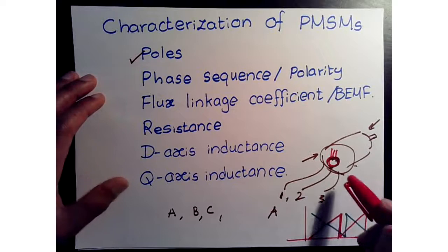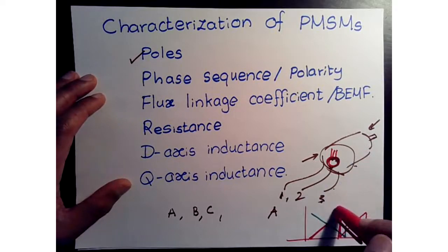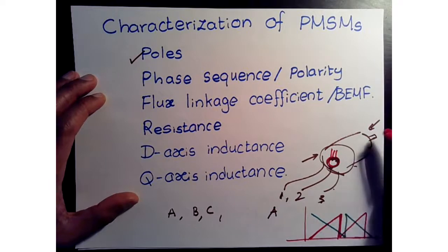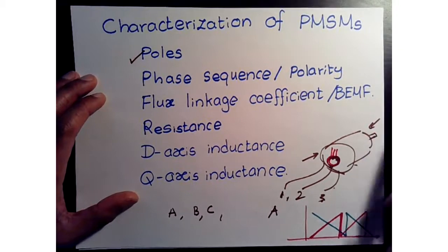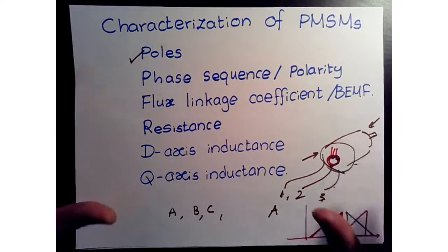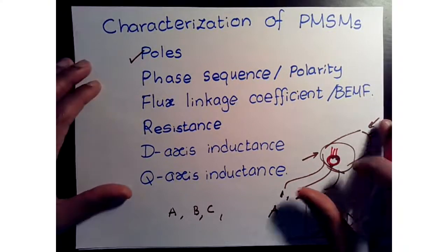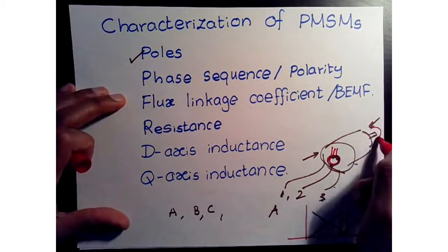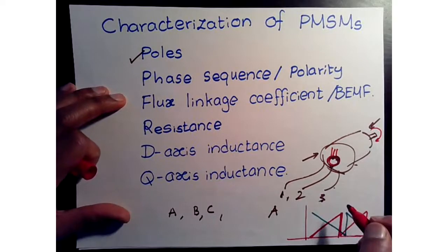Now, in order to set up this phase sequence, if you have a position sensor, you can monitor the position sensor. You will have to rotate the shaft with another motor or another power tool that you can attach to the shaft. Make sure it's stable, the machine is bolted down so it doesn't move around, and then you'll have to find some mechanism to rotate this motor in a certain direction.